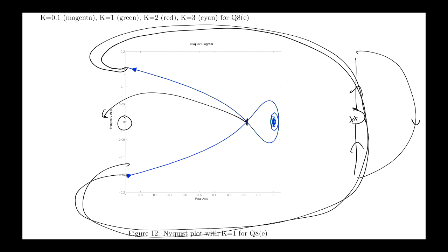All right, well, the last bit here is about steady state error, and it confirms what the internal model principle says, that if you've got an integrator in the controller, then you can get 0 steady state error for step changes in a plant input disturbance. But of course to apply that you need the closed loop to be stable. So that's the first thing to check, and we've verified that that's the case for sufficiently small gain K.